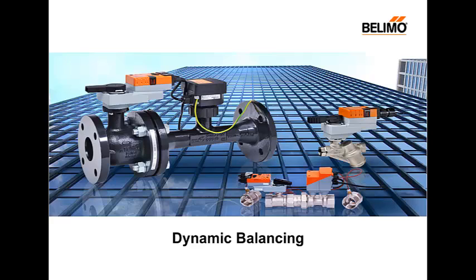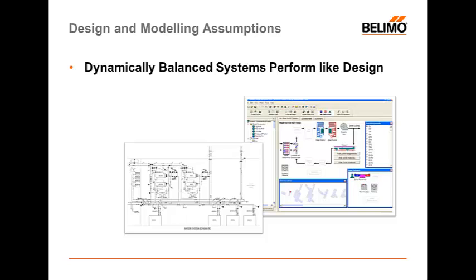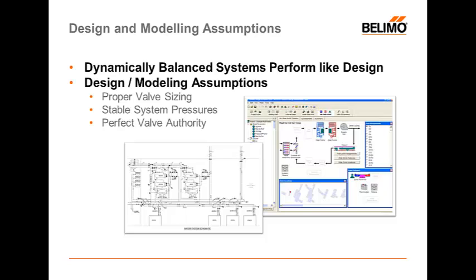Let's go ahead and take a look at what we mean by static balancing versus dynamic balancing and how each of them influences your hydronic system. As we get started here, it's important to point out that the majority of the energy modeling softwares that are available commercially assume your system is dynamically balanced from a hydronic standpoint. And the reason that they make these assumptions, and assumptions is probably an unfair word, really what happens is that they ignore some of the points that become problematic in a statically balanced system.